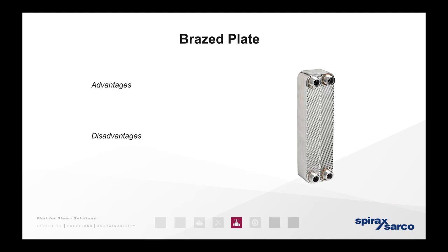When it comes to the actual materials, it depends on the CIP you're using for that heat exchanger. So it will be chemical compatibility with the secondary media you have, but also CIP. So steam doesn't care what material it is really. It's more to do with the secondary and the CIP chemicals themselves. Yeah, so it's compatibility. I would agree with you there.